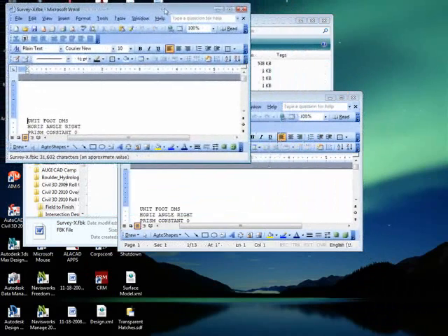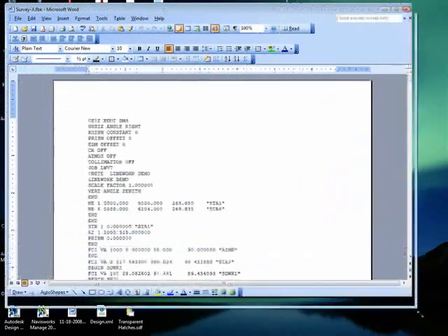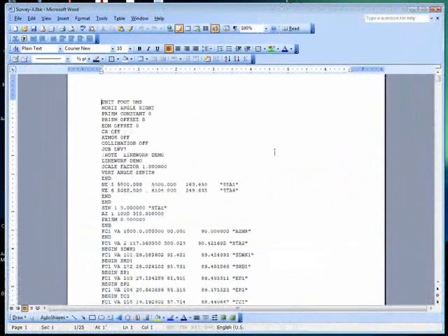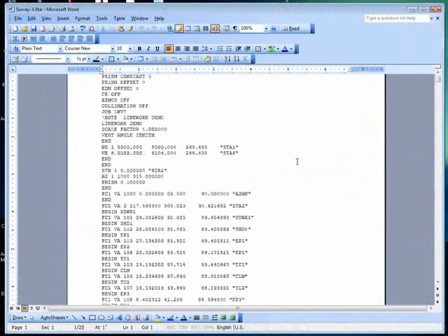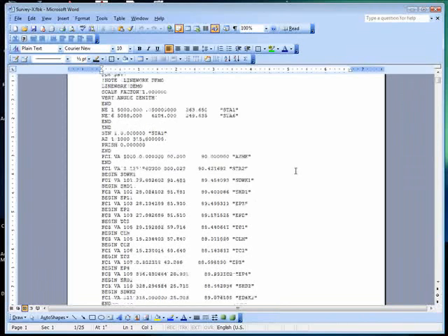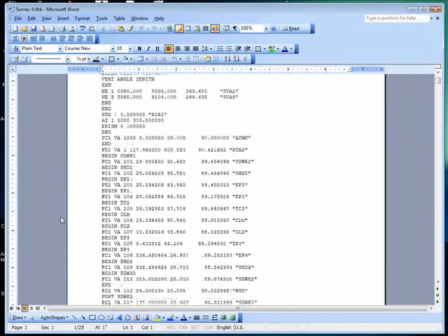And we'll start with Fieldbook X. Let me drag this out where we can see it a little better. Alright, so Fieldbook X. This is a typical entry that we would see in a field book. I'm going to highlight this line right here. So here we're beginning a top of curve line, and we've got our point number, vertical angle, horizontal distance, azimuth, and a description. Now, like I said, this is our typical field book format, what we're used to seeing.